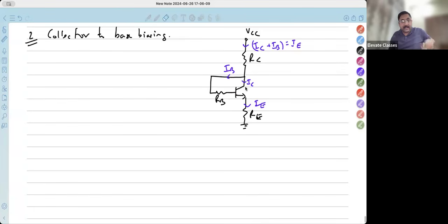Collector current is the one that enters the collector terminal, not collector resistance. RC resistance से पास होने वाला करंट collector current नहीं होता. इसमें डिफरेंस याद रखना इस टाइप में. Now use input KVL, output KVL.